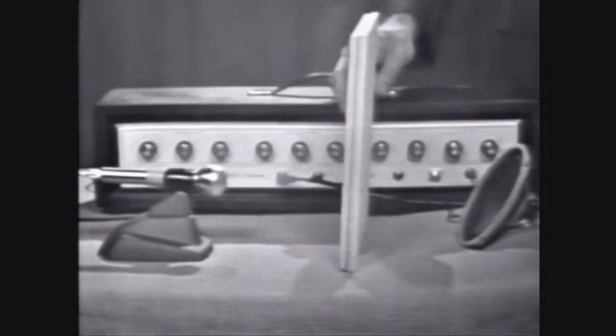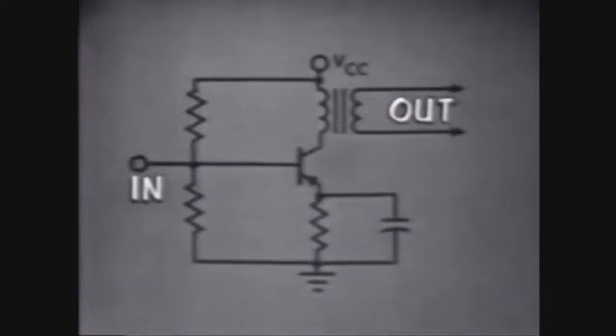But what is the frequency of oscillation? In the LC circuit, we found that frequency is determined by L and C in the tank. Now, the same thing is true in the amplifier that oscillates. But since there is no frequency determining device, the frequency of oscillations is determined by distributed L and C. That is, the input capacitance of the amplifier, the inductance of the leads, or any inductors and capacitors in the circuit. Very difficult to predict the frequency.